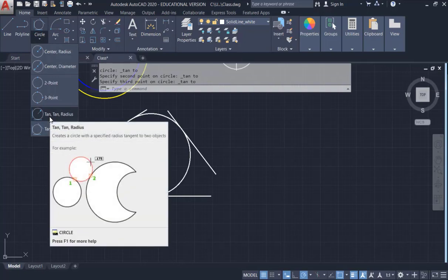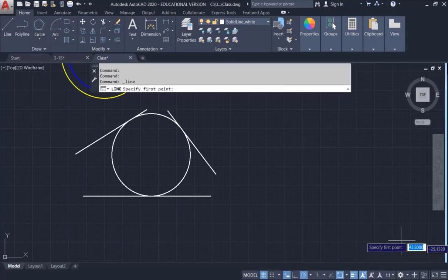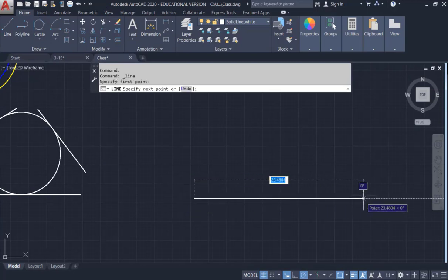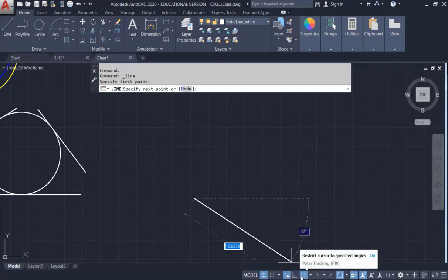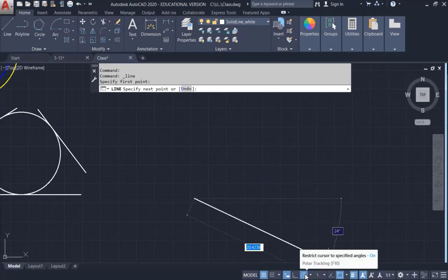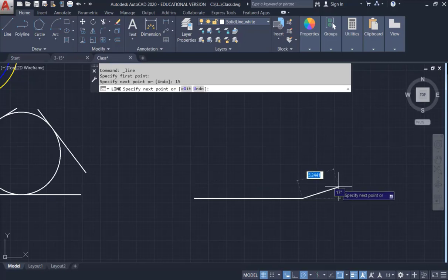That's why they have this function. So let's draw another tool. Not randomly. Let's draw one line, with the length 15, because you have this snap on. This snap is still on, so you can get the 0 degrees. Then the length, let's type in 15, then enter, and escape.